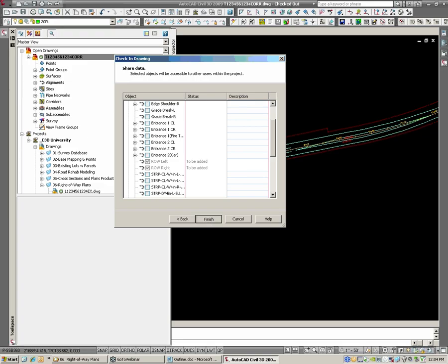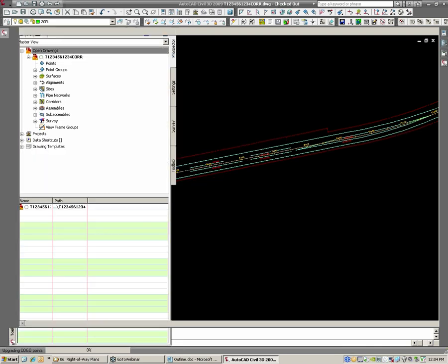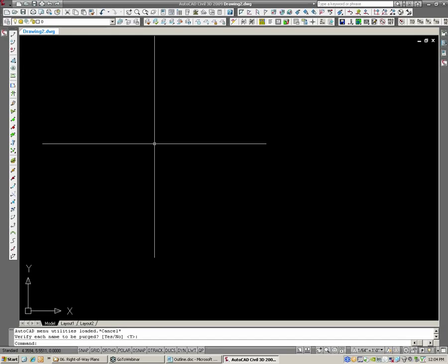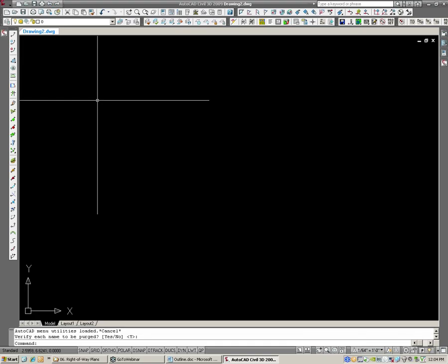So in our corridor file, that's where we'd have all the main design of the corridor model, maybe some additional alignments for right-of-way and so on and so forth. But really where we're going to do the parcels is, since it's transportation as the example here, in our T base, the T and the job number, where you have maybe some labels, and we're going to put our parcels in there as well, and some other things, but the main design is in the corridor file itself for all your vertical.